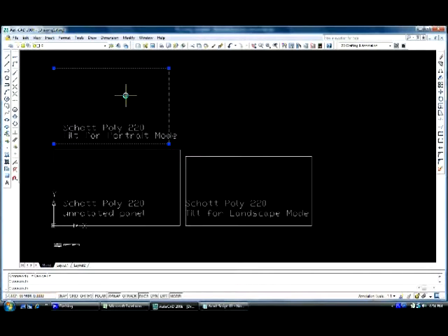Now, it's based on the tilt angle that I had in that first sheet, which was 24 degrees. All right, so for modules in portrait mode, this is the right size. If you're in landscape mode, notice it's foreshortened across the long axis for landscape mode. Okay, and again, this is all keyed off the stuff that I chose in there.